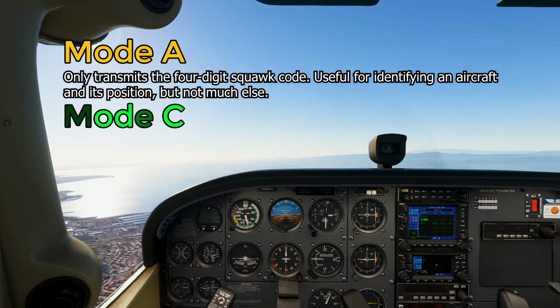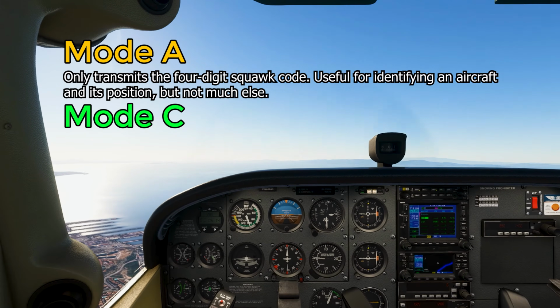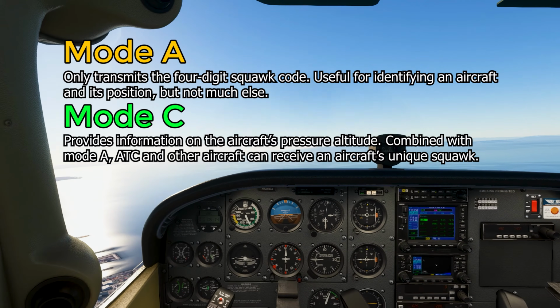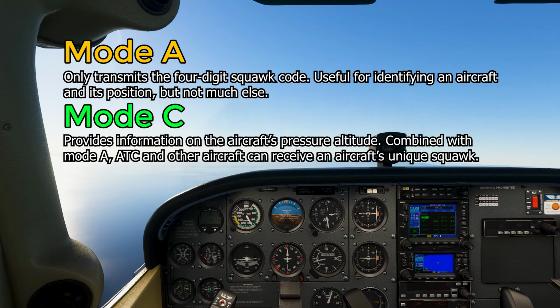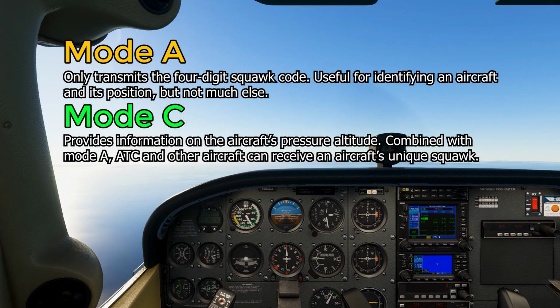2. Mode Charlie. Mode Charlie is the most widely used transponder mode. Mode Charlie provides information on the aircraft's pressure altitude. Combined with Mode Alpha, ATC and other aircraft can receive an aircraft's unique squawk code, position, and altitude. This combination of Mode Alpha and Mode Charlie is normally just referred to as Mode Charlie.